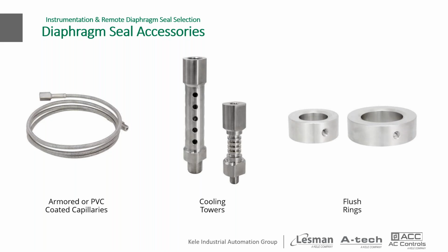Flushing or bleed rings are used with flanged diaphragm seals, particularly the flush flange, but they're used for flushing or venting the process fluid or to provide access for field calibration. Though typically used on flange seals, we've even seen some folks use these as a pressure tap on the inlet or outlet of a flanged valve.